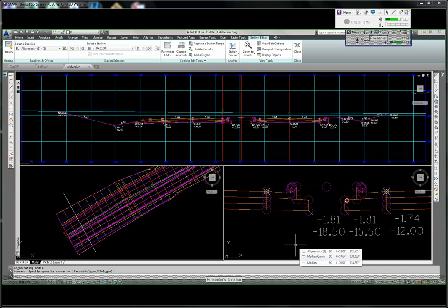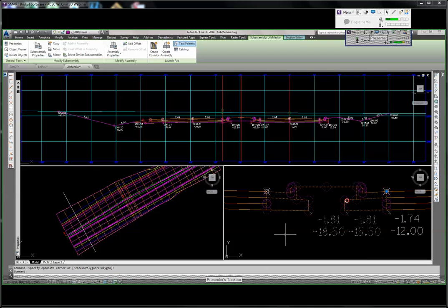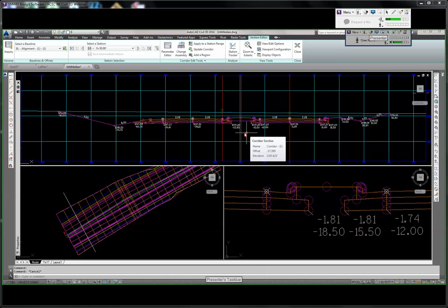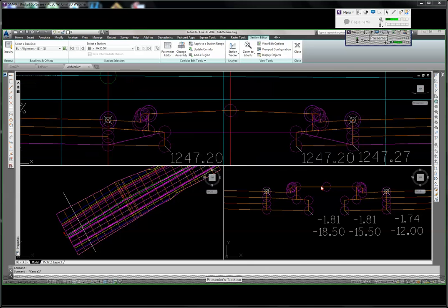If you left click on it, the whole thing highlights. You can see that actually better if I just hover over it. The whole thing highlights because it is one piece. Now, some of the things that you can control on this are the targeting of the median point. There's actually a median portion in here, and you can change the median point here. That's because you can also change the slope up to the median. If I zoom in on my actual roadway design, it's showing that there is a slope involved in this that's not showing in the layout mode.